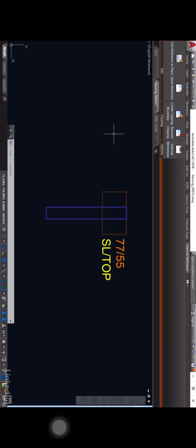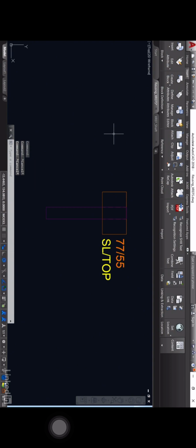I'll just close the External References palette, and it takes us back into the drawing. I'll hit Escape now just to deselect the reference file, and you can see that's how you use your XREFs to reuse design content when you're working in your AutoCAD drawings.